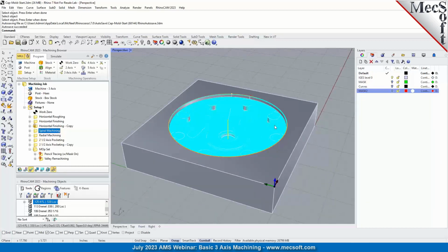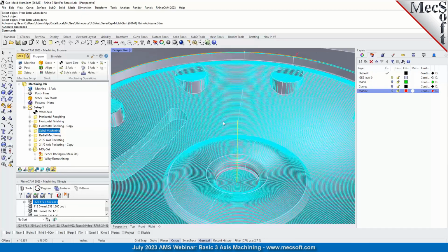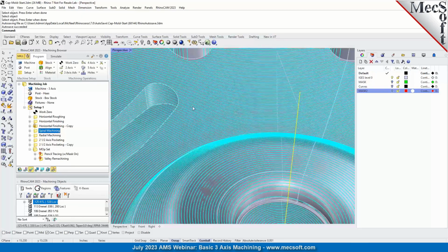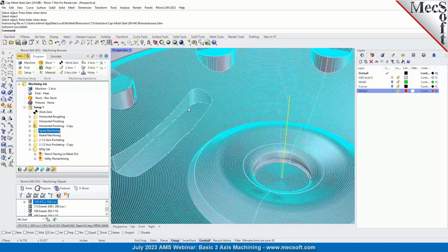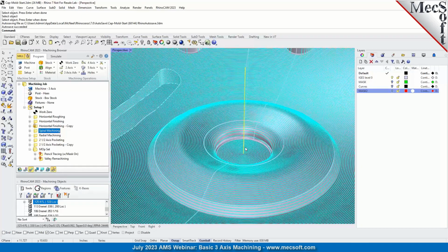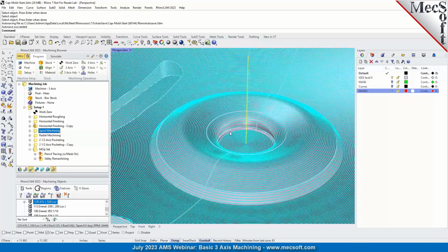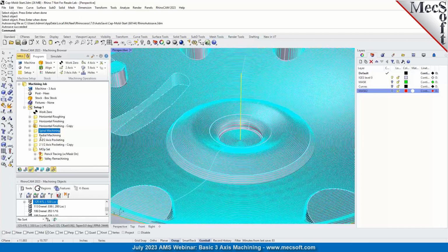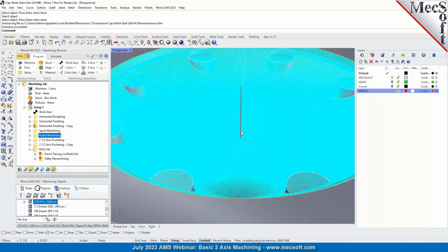If you're slicing in the Z direction, you can put an arc. But radial and spiral are in neither of those planes, so you cannot fit arcs. So that's one thing that you need to be aware of. If you need a tight surface finish and you need to use spiral or radial, just make sure you adjust your tolerance value low enough to get the surface quality that you need. The same for the radial.